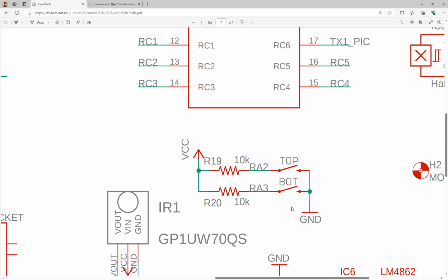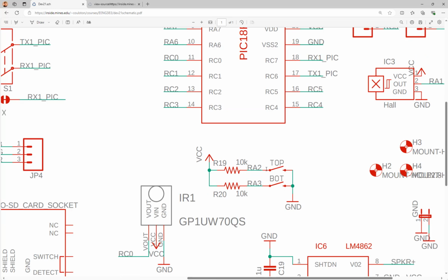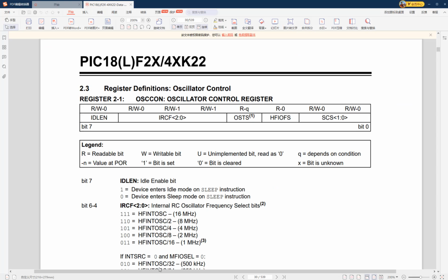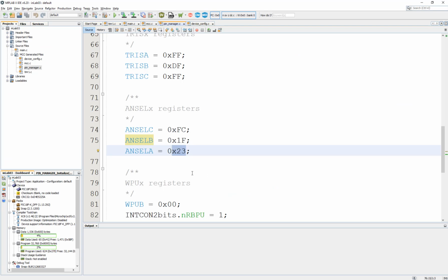Just a schematic. So this is RH connected to RA2 and this is connected to RA3. That's enough, it already shows you everything. If you press it, it's shorting this pin to ground, so you are reading a 0. Okay? So I'm just telling you how to find out the resources from the data sheet, but there are so many things that I'd have to spend Friday probably to talk about it. But in the lab tomorrow, you know what to do.